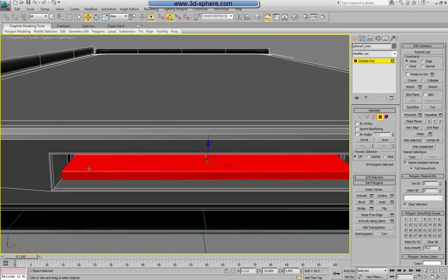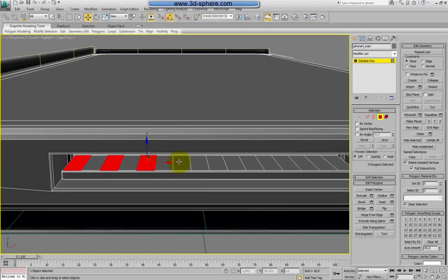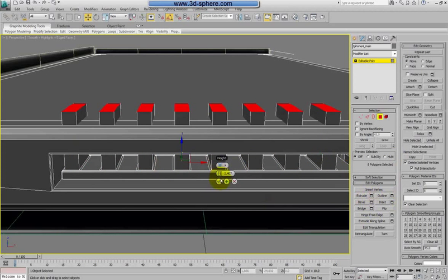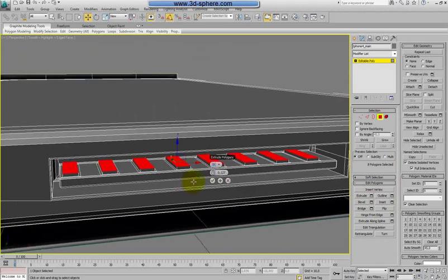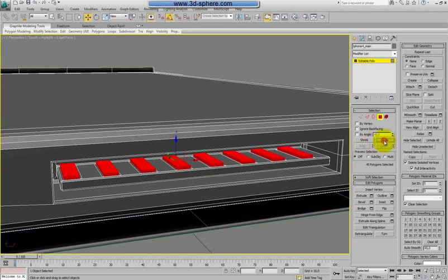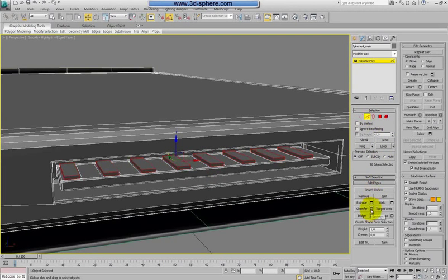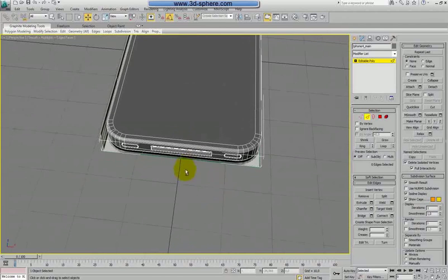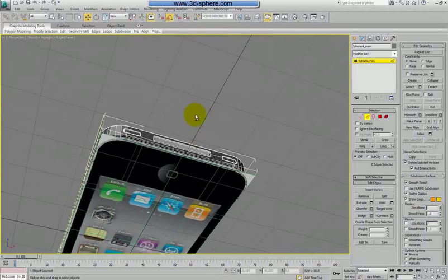Now select this poly, every second poly, inset it a little bit and extrude it just a little. Press OK, grow, Control Edge, and chamfer. This we need to chamfer like this. So okay, we have the plug, which I hope will not be so big for our model.